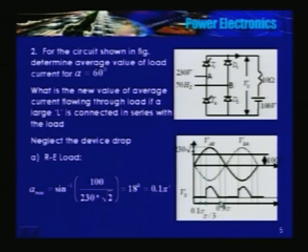So current becomes 0 at 0.91 pi. I repeat, you could have triggered the thyristor at 0.1 pi. If I had diodes D1 and D4 instead of T1 and T4, D1 would have started conducting at 0.1 pi and would have stopped conducting at 0.9 pi because they get forward biased at that instant.